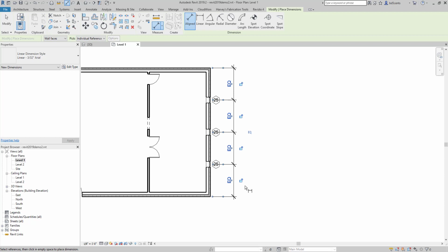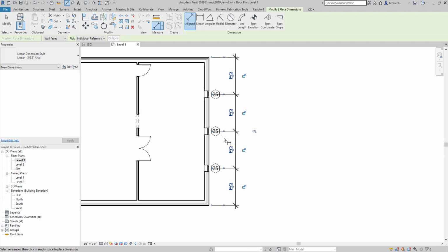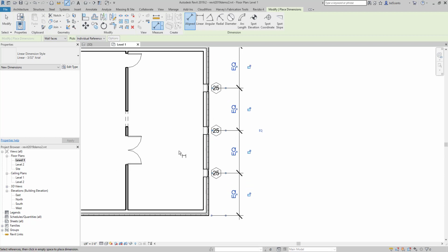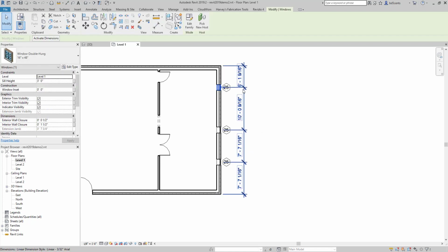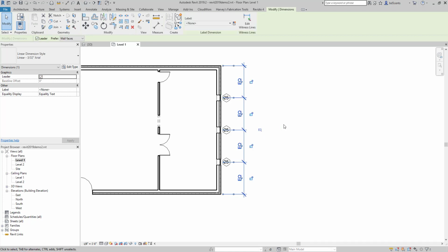So do you see these blue dimensions? The blue dimensions no longer are there. They're permanent black dimensions, and they can be locked and unlocked. You can see the uneven sizes between the windows prior to this equal size being locked. Now they're unlocked, meaning I can move a window and it'll adjust those. But I can then hit that equal button and it'll go back.